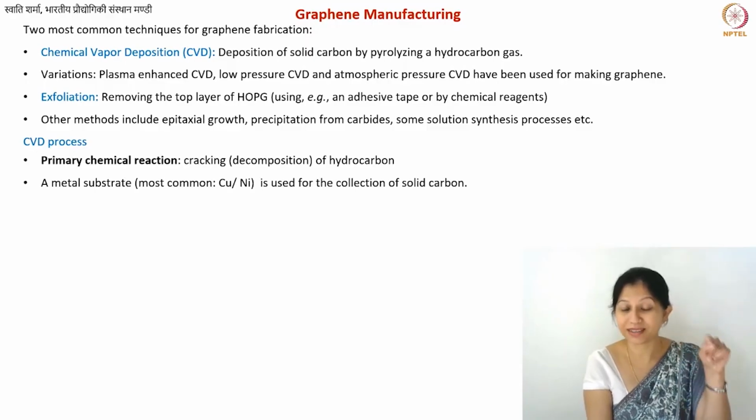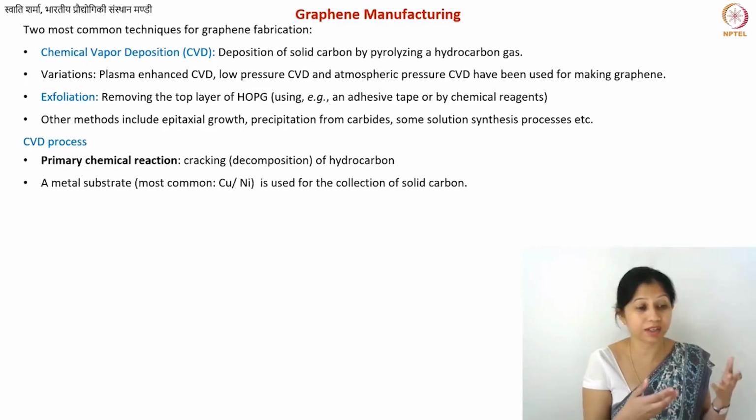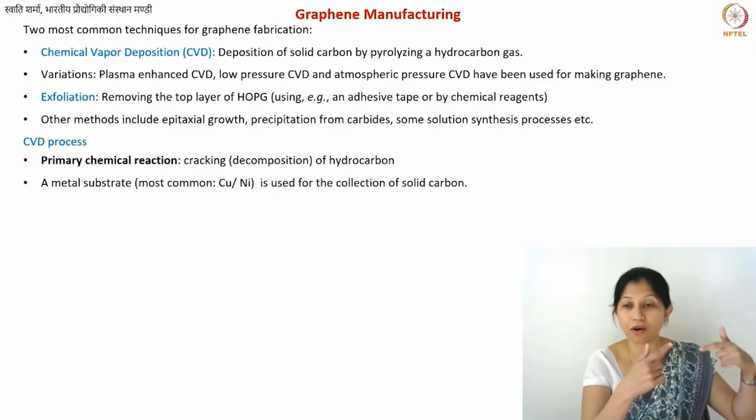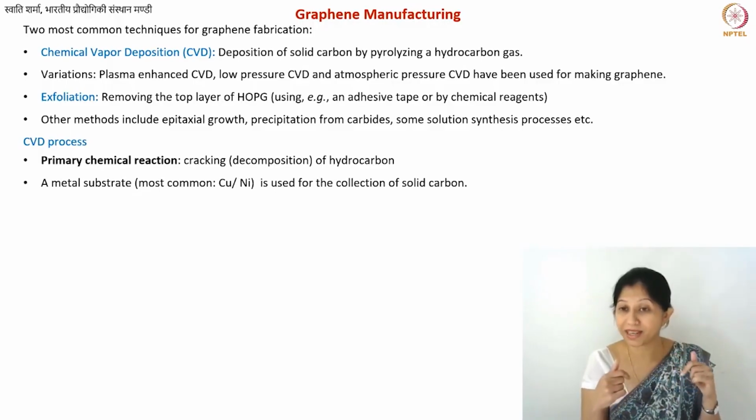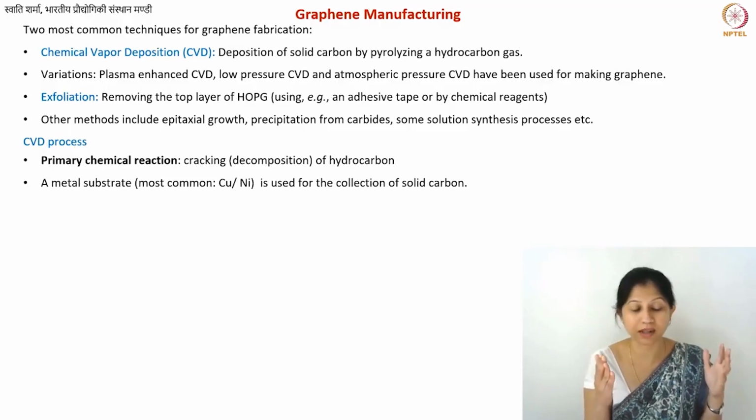So again, using the CVD process, what you can do is take that pore containing structure, put it inside your CVD reactor, and then deposit layers of pyrolytic carbon inside your pores. This process is very long, and of course it's relatively expensive, so it's only performed for rather high-end applications. For example, some very high-end composite materials, carbon-carbon composites. So in that case, you can perform this. My point here is that you can perform CVD on carbon substrates as well.